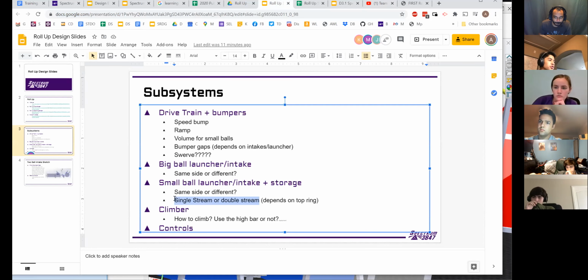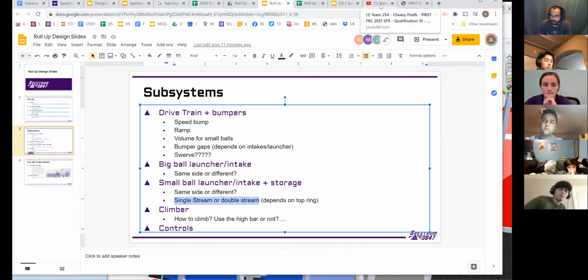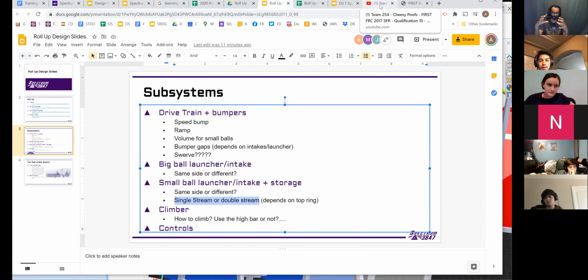So why is double stream easier than single stream? Okay, so that was the thing. Thank you, that was what I was trying to get to. You don't have to force the balls into a single row, right? So there's less opportunity for them to jam because you just have to get them into a row of 2.